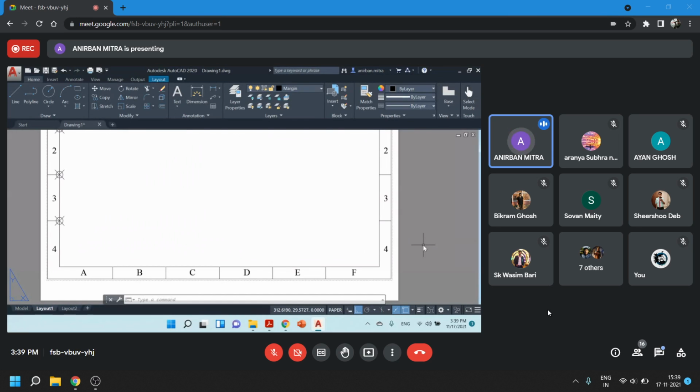The next thing is the title block. The title block can be created quite easily. I will select this corner point and start a line. Relative command @ let's say 50, angle is 90. Go to this position and now we continue the line. So @ 80, the angle is now 180, and we can drop a perpendicular and stop here. So that should be our title block.